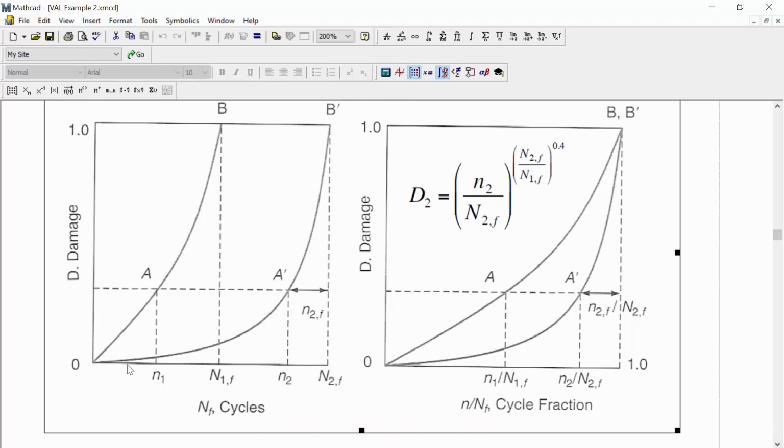Here we're illustrating, say we have 2 completely separate fatigue tests. One that's run at the first step's stress amplitude, and another one that's run at the 2nd stress amplitude. So these are 2 independent fatigue tests. What we're doing when we're applying this nonlinear rule is we are normalizing by the cycles to failure in both of those independent experiments, and then we're finding an equivalent damage.